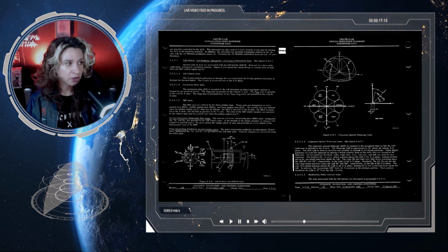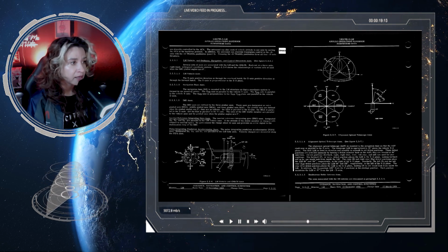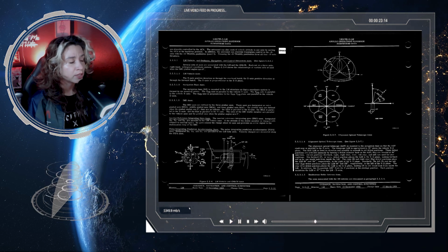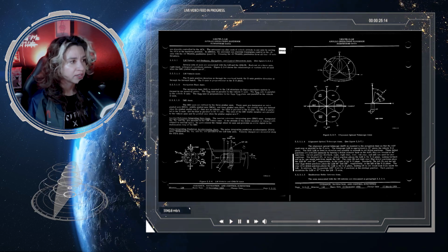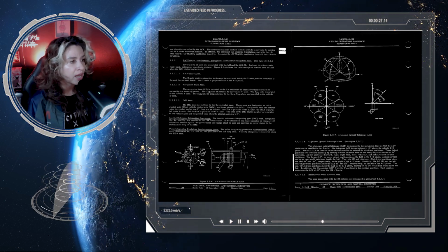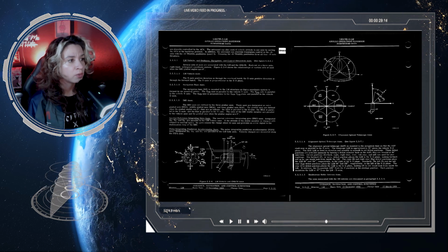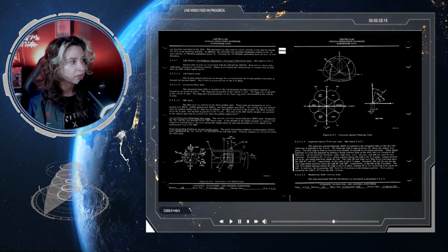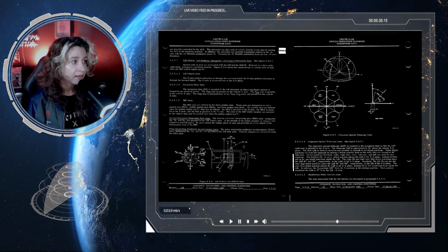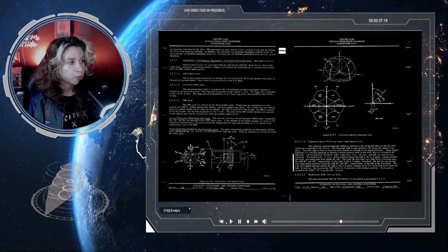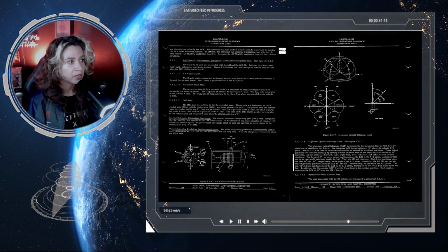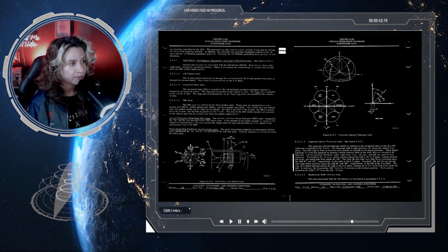The navigation base, or the NB, is mounted to the LM structure so that a coordinate system is formed by its mounting points. The YNB axis is parallel to the vehicle y-axis. The XNB axis is parallel to the vehicle's x-axis. The ZNB axis is perpendicular to the XNB-YNB plane and parallel to the vehicle's z-axis.